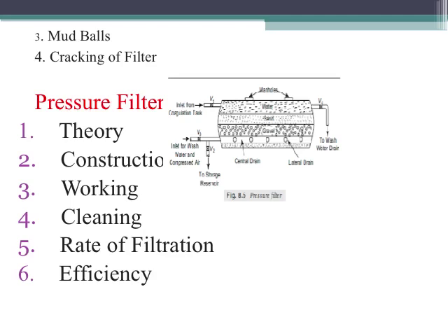Moving on to the construction, it is a closed cylinder made of steel sheets by riveting. The diameter of the cylinder varies from 2 to 4 meters and the length varies from 4 to 8 meters. Two manholes are provided on the top for inspection purposes, and it consists of an inlet pipe from the coagulation tank and an inlet for wash water.